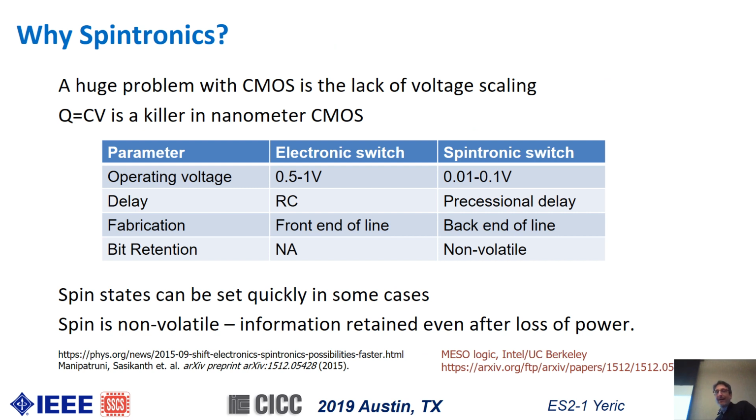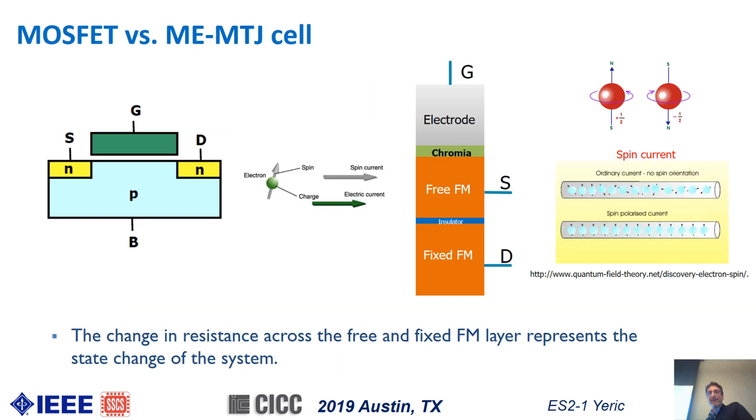Spintronics is the other technology that gets a lot of press at the moment, and it is very attractive in the same sense. The big problem we have with CMOS is charging these nets up and down half a volt. That's where we get our problems with power and performance. And Spintronics can do stuff at a 10 millivolt level, right? So it's very attractive from that perspective. And it doesn't need a big refrigerator like superconducting per se. So it's very attractive in that sense.